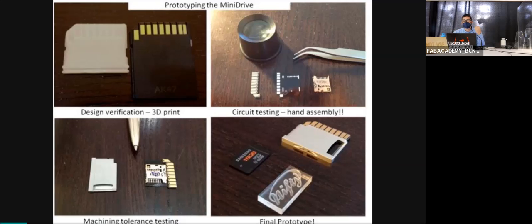When you have tested your tolerances, you still need to do your electronics. For that part, you can use the traditional chemical path of electronics, or you can produce your PCB circuits with a small milling machine. When the electronics fit your 3D printed prototype, and everything seems to fit inside, let's jump to the beta stage of the product. Now is the time to change to the final materials. This is the final stage of prototyping, when you actually produce the final part in aluminum, and you do it by adjusting the final tolerances of your product. So these are some prototyping steps that you take.